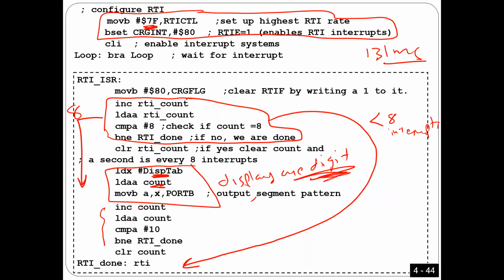That's what I did here. Increment the count, you can see here, guys, increment the count. Now I'm gonna compare count to 10. If it is less than 10, I'm done. If it's not, I have to clear count. So simple.